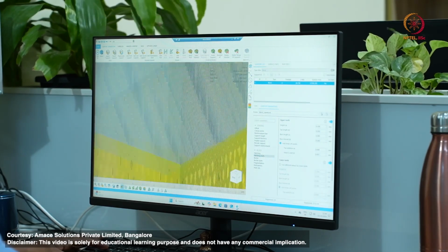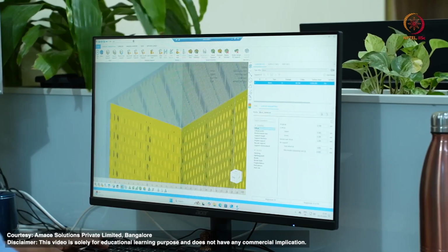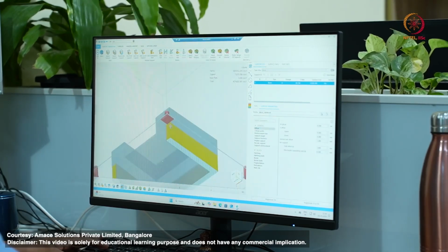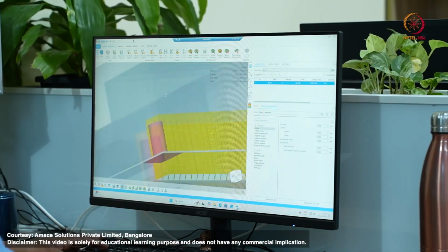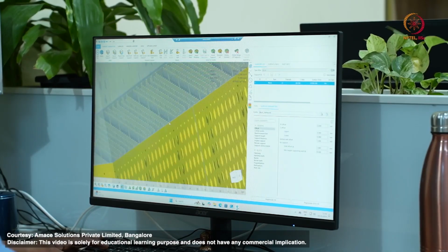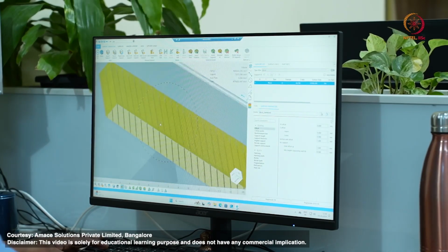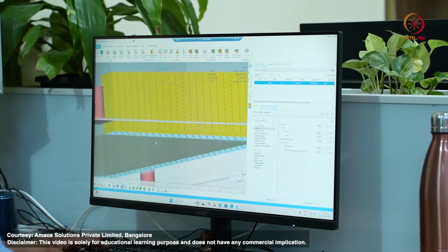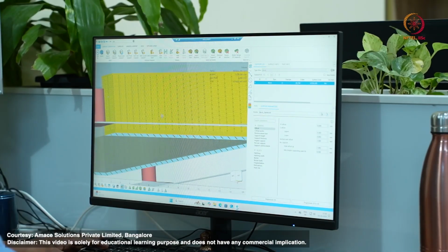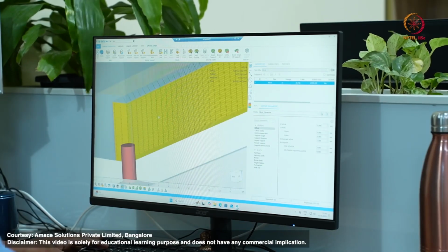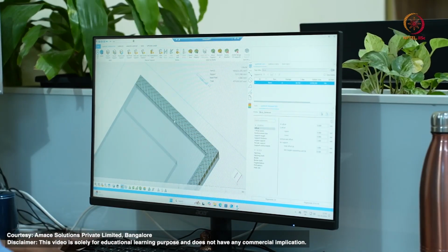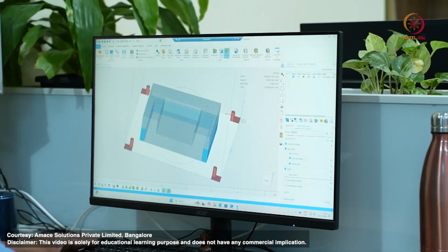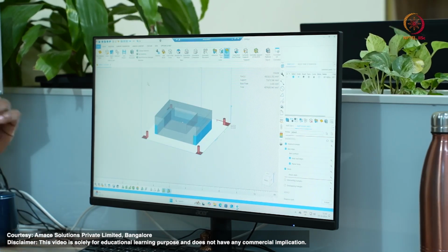So if you see here, you will be able to see. You can change these parameters according to your machine as well as the printing parameters. In block support, the main factors we need to consider are the perforation which is required for the powder removal from the supports, then fragmentation for ease of support removal. So once we have done this support generation, we can slice the file.